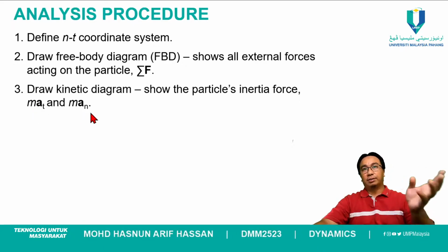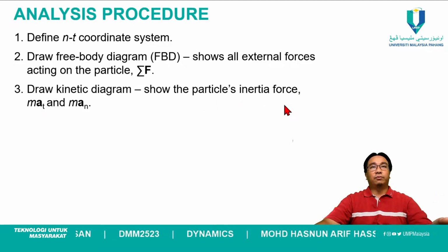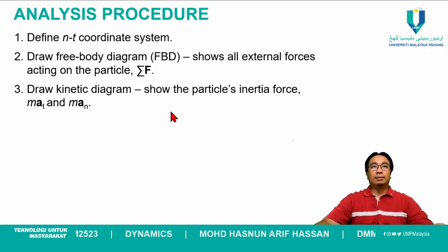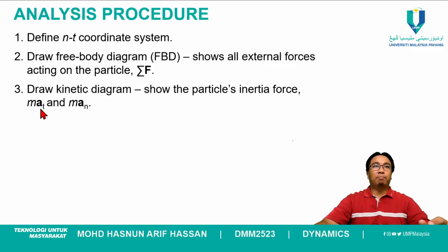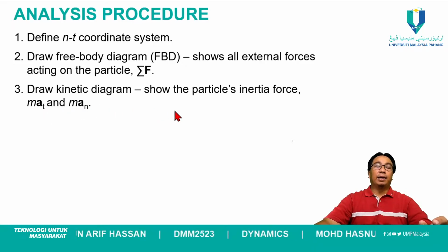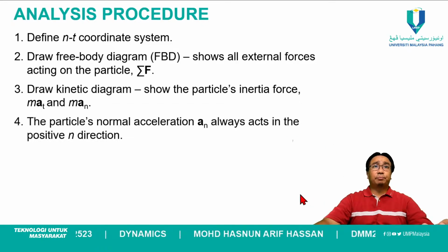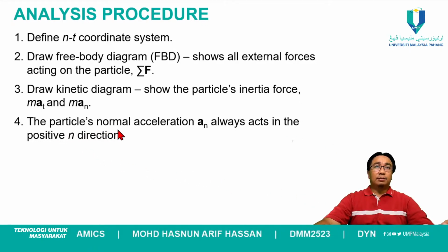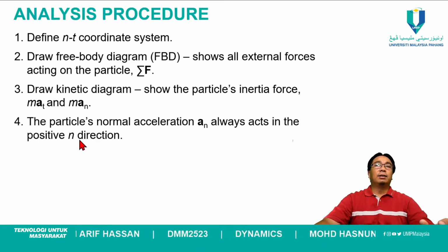In the previous class, we showed the inertia forces in terms of X and Y axis. For this subtopic, we are showing MAT and MAN, tangential and normal components. And the particle's normal acceleration always acts in the positive n direction.